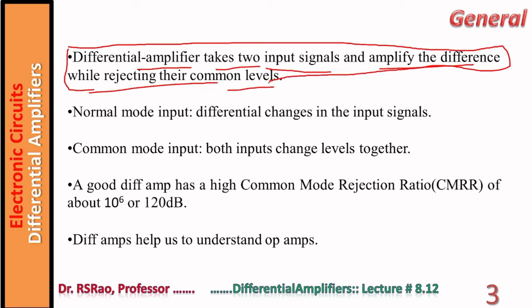There are 2 input modes: normal mode input, common mode input. Normal mode input means differential changes in the input signals. Common mode input means both inputs change levels together. Common means common to both the inputs.